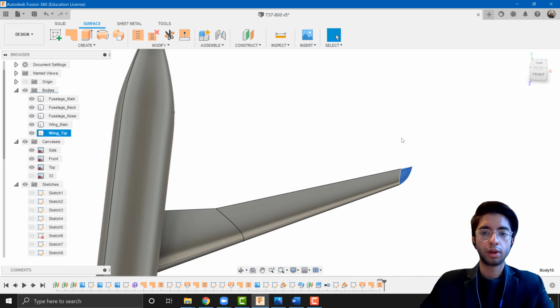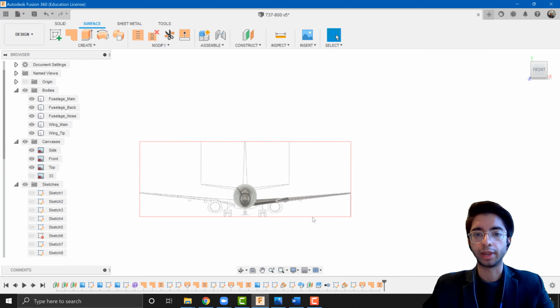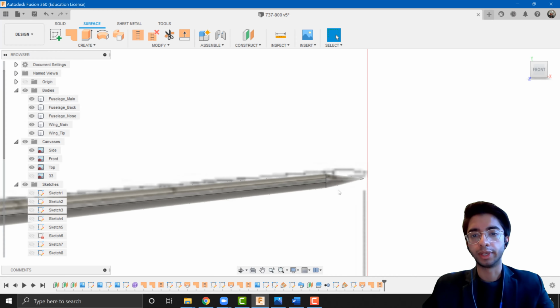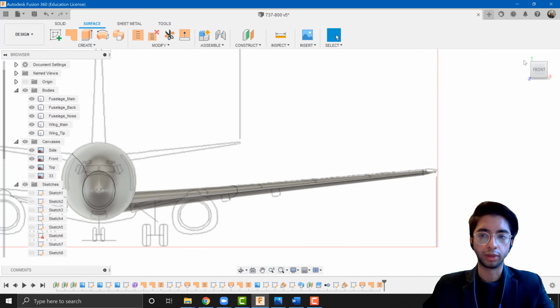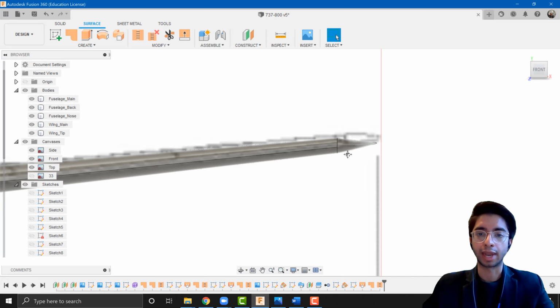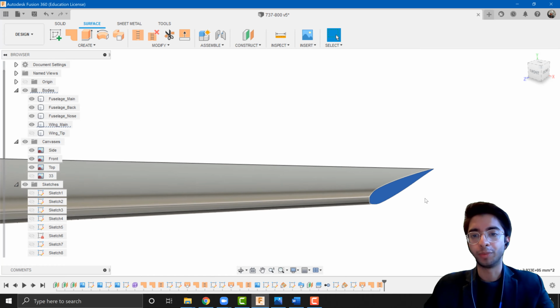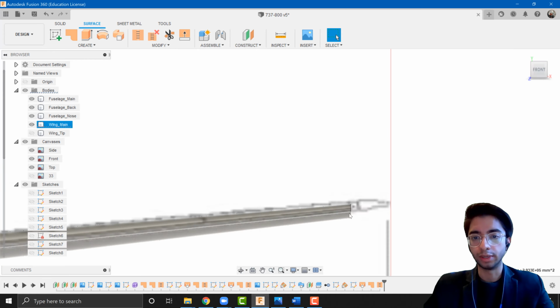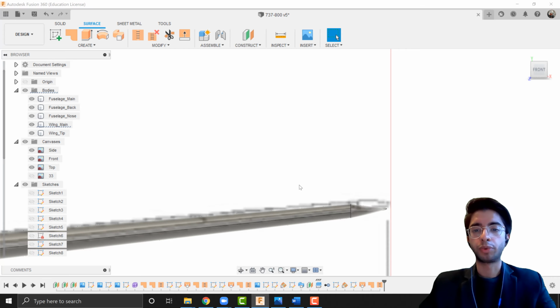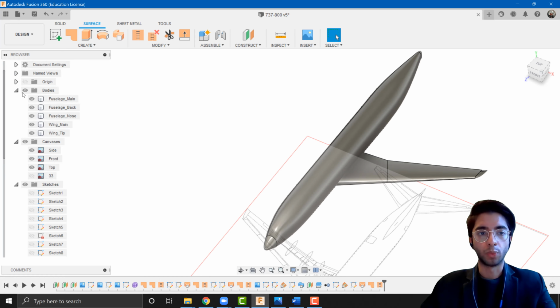All right, so if the aircraft that you've chosen has a more complicated wingtip, what you can do is similar to how we swept the wing. So first by making an airfoil, then from the top view, we swept out the path that it needs to take. What you can do for the wing tip is exactly the same thing. So you start off with the airfoil over here, and you basically sweep a path for it in 3D such that it takes a shape like that. And it should be able to do it pretty straightforward again. Okay, so that's it for the main basics of the wing.